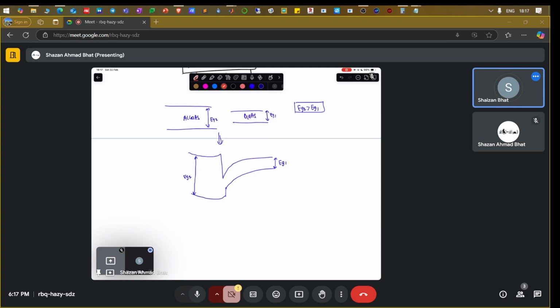And in here, this particular gallium arsenide is unintentionally slightly n-doped. So the Fermi level is going to be closer towards the conduction band, and when you draw the Fermi level in this system, it will look something like this. You can see that at this particular position, the Fermi level has crossed the conduction band of gallium arsenide. This is aluminum gallium arsenide, and this is gallium arsenide.